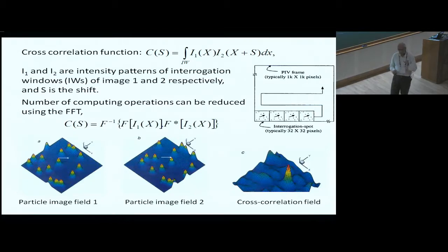In fact, one can go back later and look at the individual particle displacements to get a finer, or better, velocity field in terms of the variation within that window itself. There are a lot of techniques being used to smoothen out the data finally. Because if you want to get, for example, vorticity, then you need the gradient of velocity, and how you obtain that gradient depends on all these fine things you do in the processing.